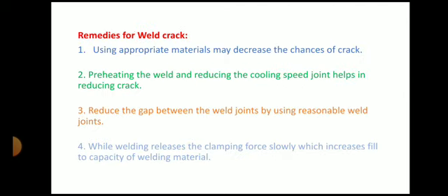Remedies: using appropriate material may decrease the chances of crack. If your material is having enough ductility, so use appropriate material. Then preheating the weld and reducing the cooling speed of the joint help in reducing the crack. Preheating is one of the processes. Before welding we preheat the material, that is nothing but preheating, and then reducing the cooling speed.